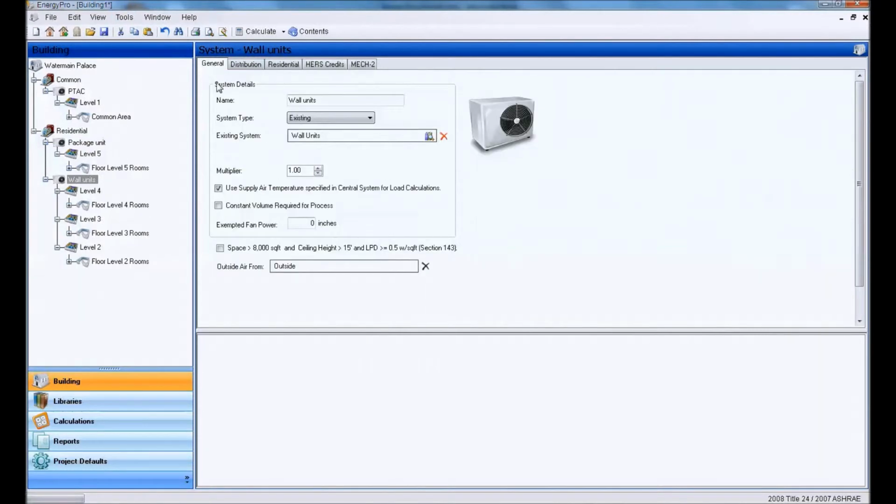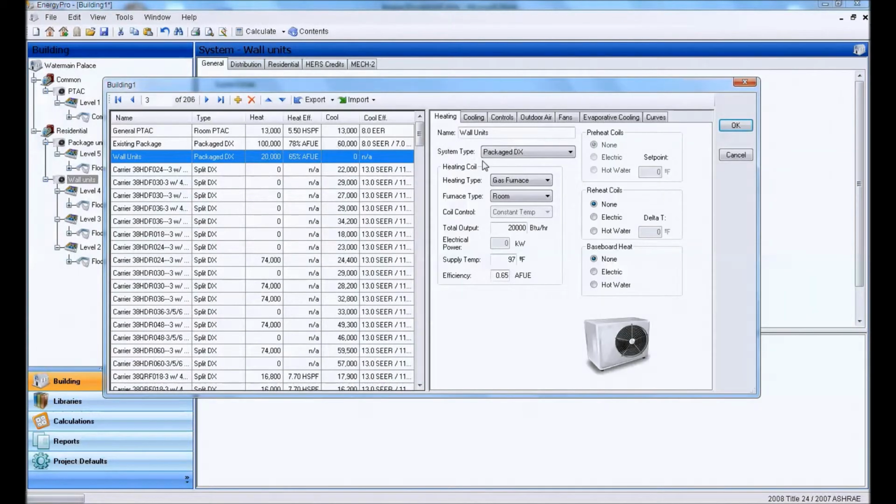And again, if I had a hydronic system that served these units, I would set these wall units to radiators. I would set this up as something like a 4-pipe fan coil or a split system. Let's use a split system for now. And I would set that efficiency based on my heating hot water boiler,